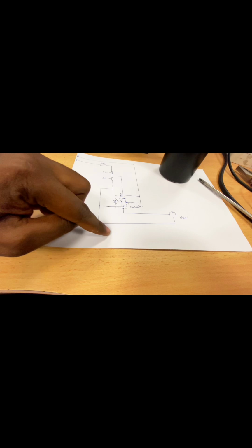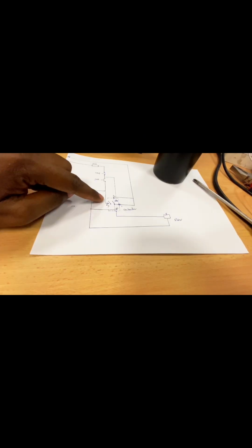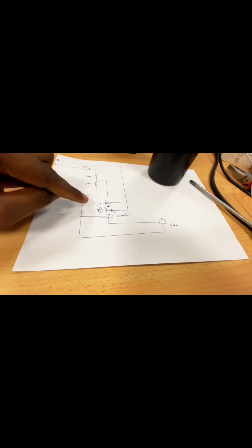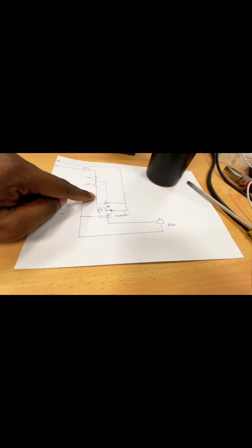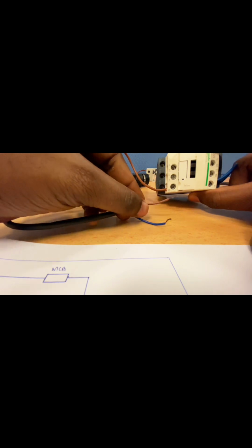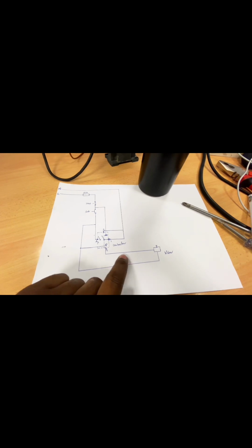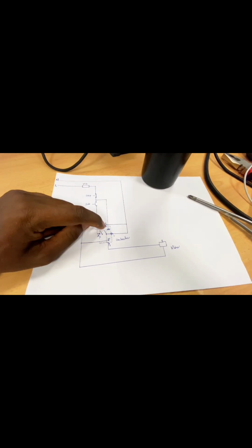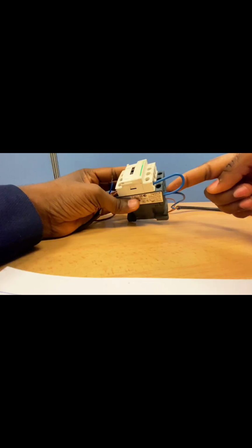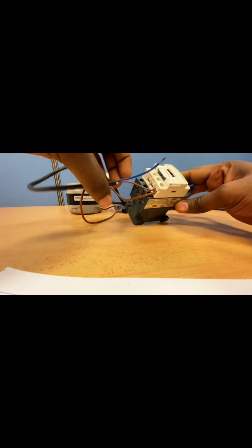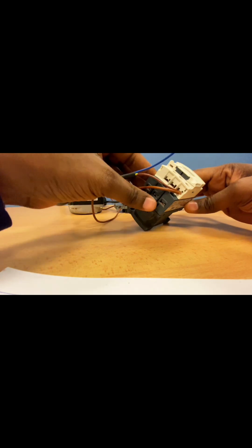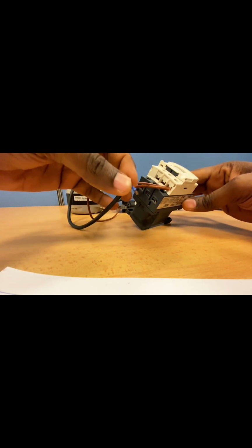From start to the A1 connection, we are going to make our line connection of our motor and loop it at A1 as indicated in the diagram. So this is our motor. We are going to connect our line at A1. Then we are going to connect our neutral at the output pole of our contactor. This is our pole input. So at the output pole, we are going to connect our neutral.